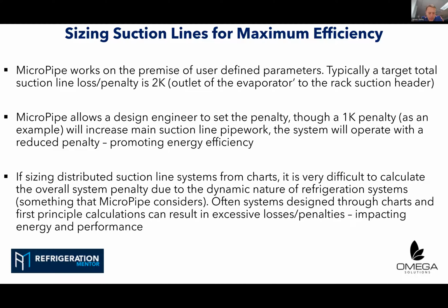Now, I've been based in the UK all my life, but what I've found out recently is that in the US especially, there are a lot of stub systems out there, which effectively have multiple suction and liquids connected to a header on a rack. And I can see the merit in that. If you're sizing off charts, you want to limit the number of fixtures, display cases or room coolers connected to that, to make the design process that little bit simpler.